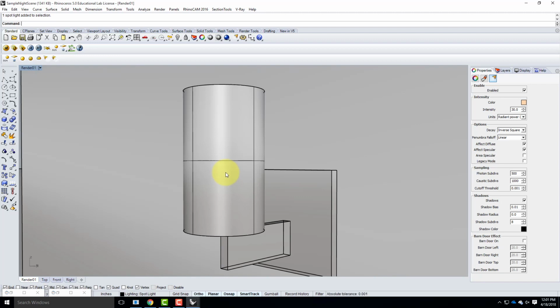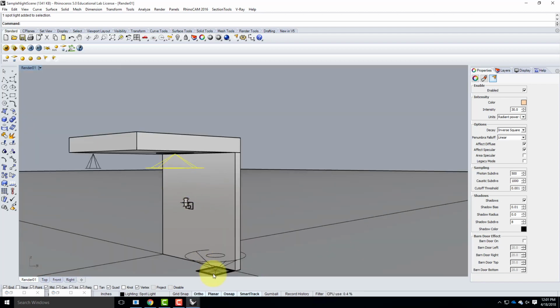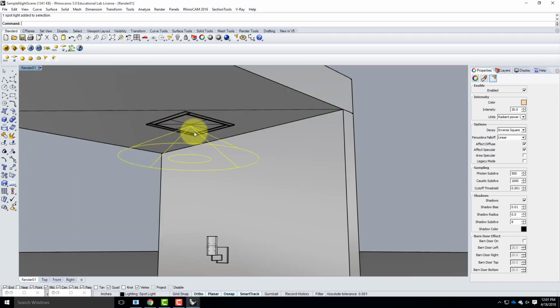What is emissive material, in fact? The emissive material is a glowing material. It's supposed to glow, but it is not supposed to light the scene. So when I created this roof tile, without the spotlight on it, it wouldn't have enough light for the scene. It'll show that it's glowing, but it won't give enough light to render anything else in the scene. Everything else appears dark. So I still need the spotlight in combination with it. So it's two parts, yeah.